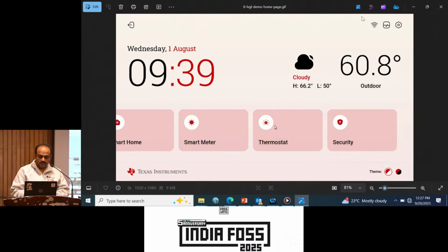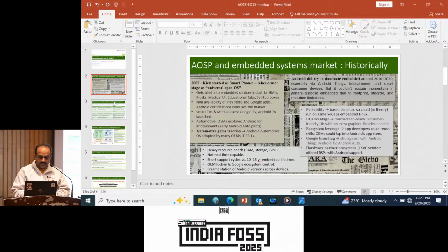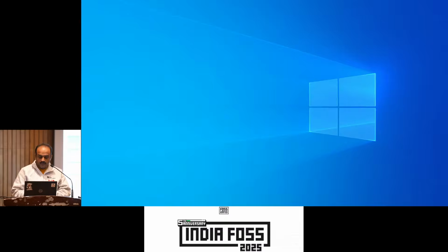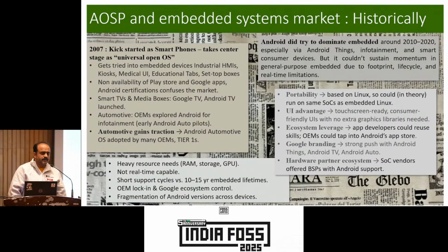So I just showed you what has historically been done in Android, and I just shared with you an embedded system of the current day. The device that I showed in my video is an embedded system running an ARM Cortex A53 dual core, with no GPU, no AI accelerators or NPU inside, and no audio acceleration, nothing.